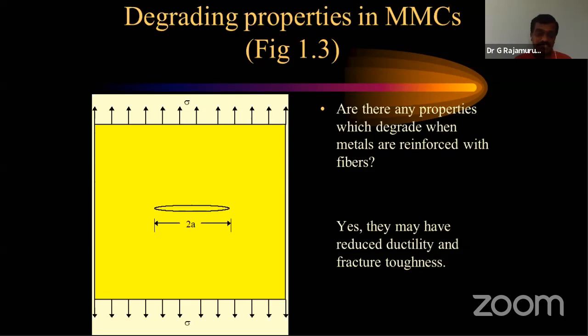In this metal matrix composite, the crack opening displacement is very important. You have to study fracture toughness, because it is more important when compared to metal. In metal, all the alloys you are going to use for the fabrication are mixed together and they will look like a phase. In metallurgical terminology, all are in the form of a phase if you see it in a microstructure.